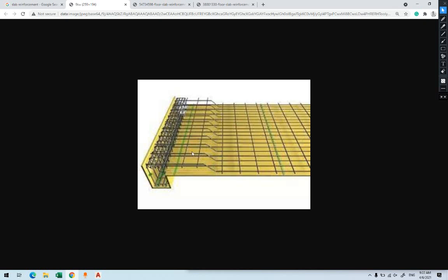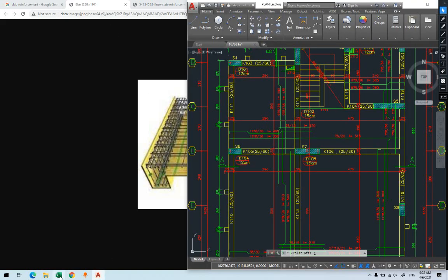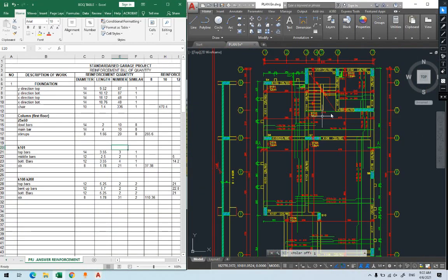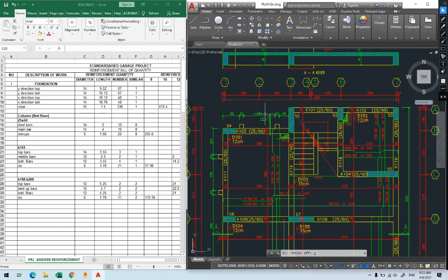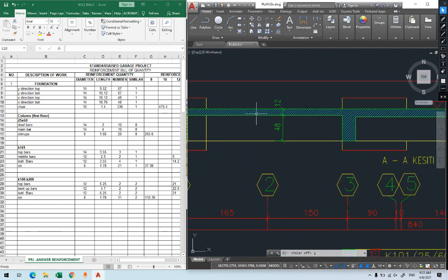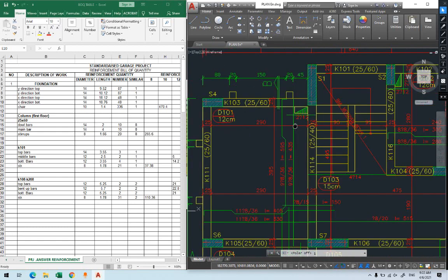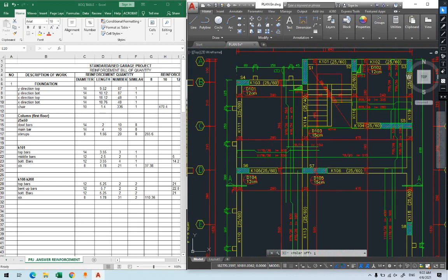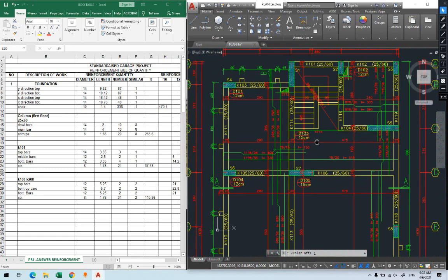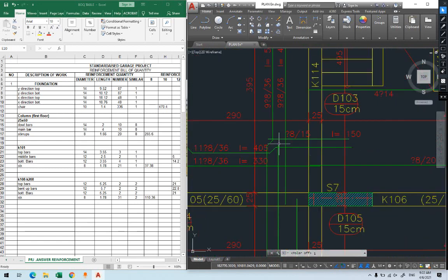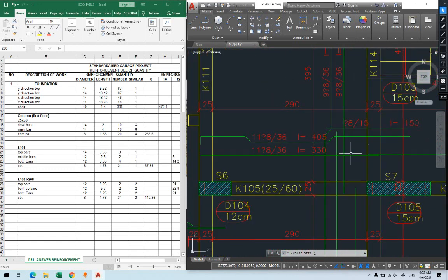So how do we know which one we have? We'll go to the plan and read from it. Now for the slab plan, we're going to go to the place where we have beam and slab. Now you don't have the reinforcement here, they didn't provide it here. Some they provide here the same way as the foundation. They'll provide some detailings here, but mainly we'll look at it on the drawings. So which ones are the reinforcement? Those are the reinforcement, we have it here.